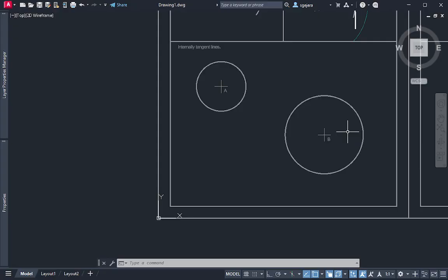Okay? Now, the other case would be externally tangent lines wherein your tangent is outside, no? So, if you created the two solutions, they will not intersect. Or if you imagine a line connecting the centers, the externally tangent lines will not intersect that line connecting the centers, but this one intersects the line that's connecting the centers. So, this is an example of externally tangent lines. So, let's go with the first case first, internally tangent lines.